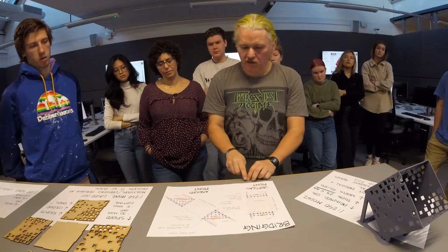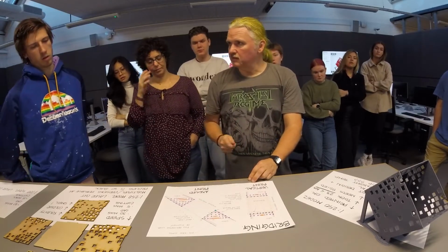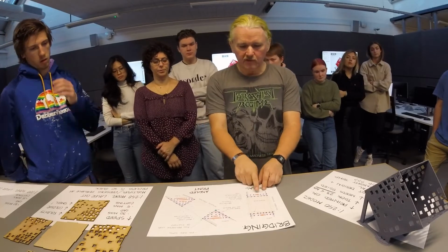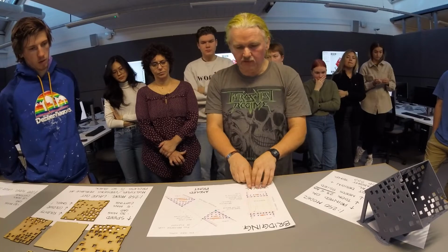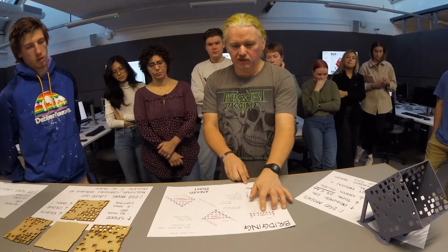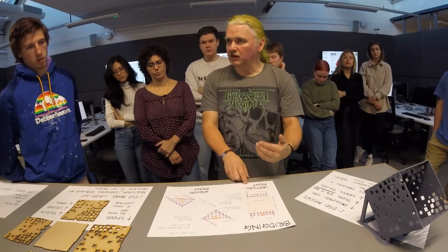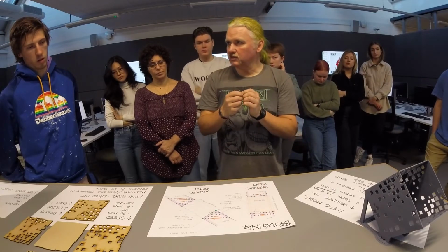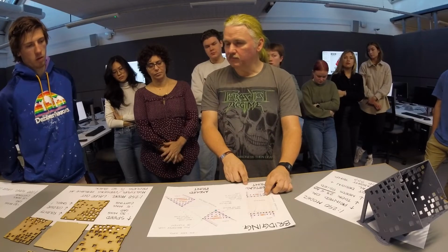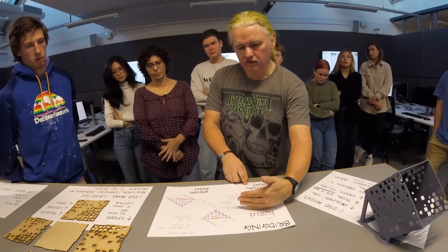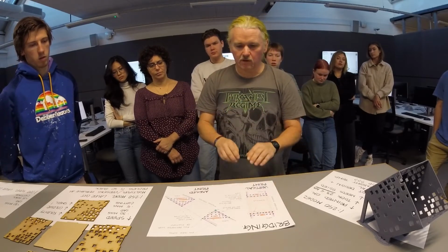Sometimes it's just straight lines. If it's a very narrow wall, it'll just zigzag and do it quite quickly. So that's what that is, simply the infill. Okay, but on a vertical wall that's got a reasonable amount of thickness, then it cannot do the bridging. It cannot just take a line across like it's throwing a rope across. So that's where the scaffolding comes in. It has to build up this scaffolding so it can eventually lay these main lines across at the top.